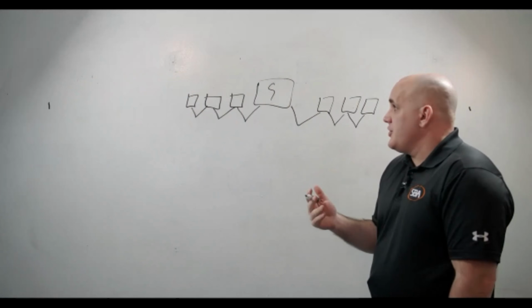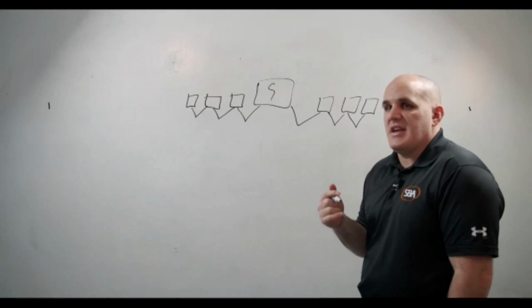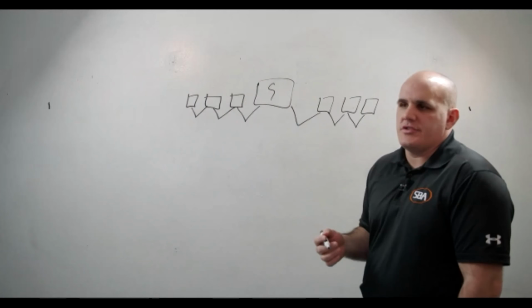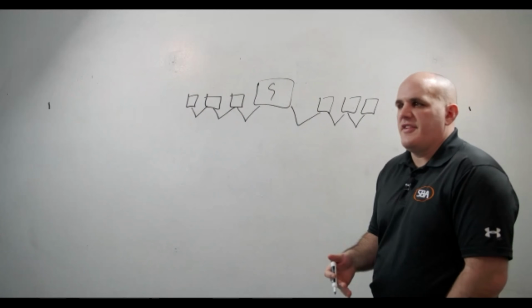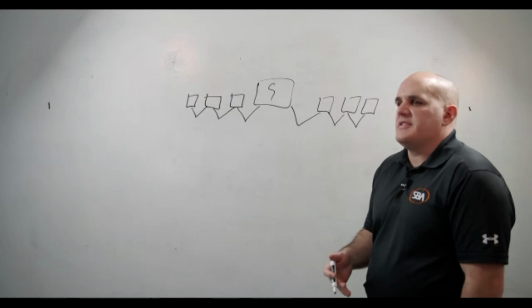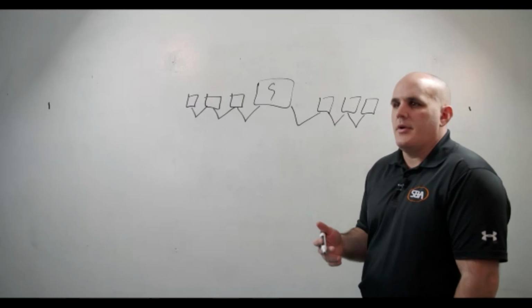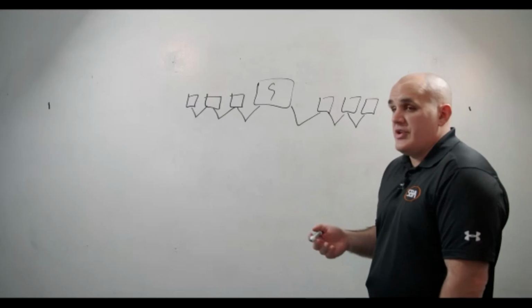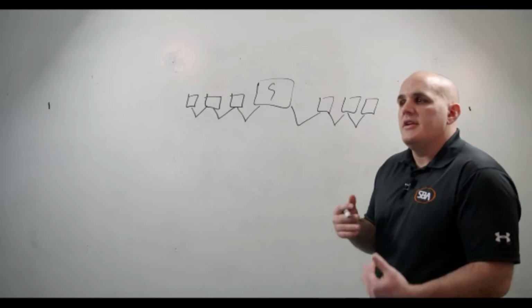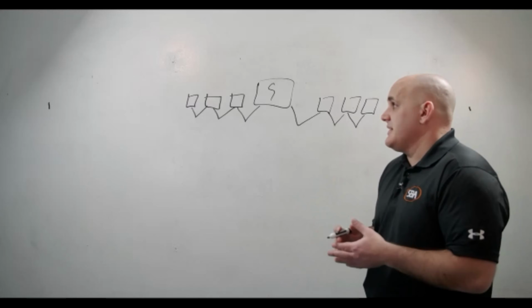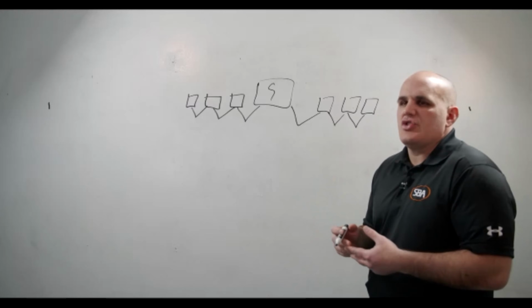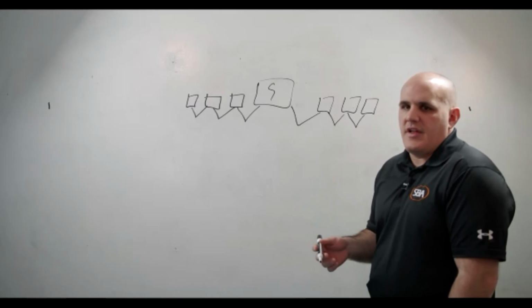How I like to approach an MSTP issue is, I go to the customer and they say the controller's offline. I say, okay, how long has the controller been offline? It's been offline since we changed the controller. All right, now we've got somewhere to start. Knowing that the controller has been offline since they changed it is going to be completely different than if we had a lightning storm and now we have 5 controllers offline.